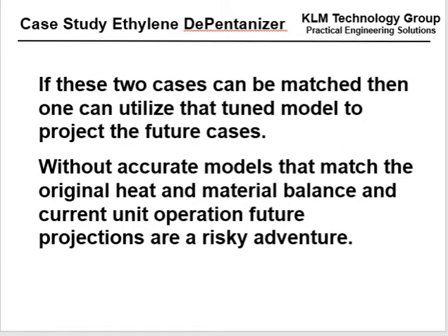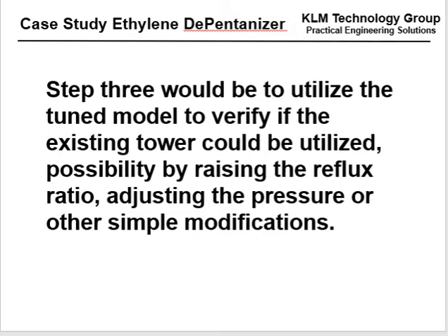If these two cases can be matched, so if the original design can be matched and you can match what's in the field today, you can then use that model to project the future cases. Without accurate models that match the original heat and material balance and the current operation, future projections are a risky adventure. Step 3 would then utilize the tuned model to verify if the existing tower can be utilized, possibly by raising the reflux, adjusting the pressure, or other simple modifications.